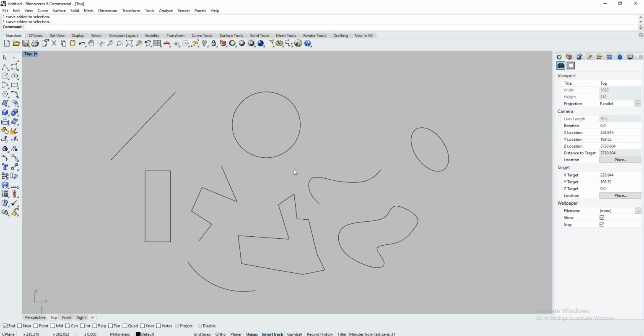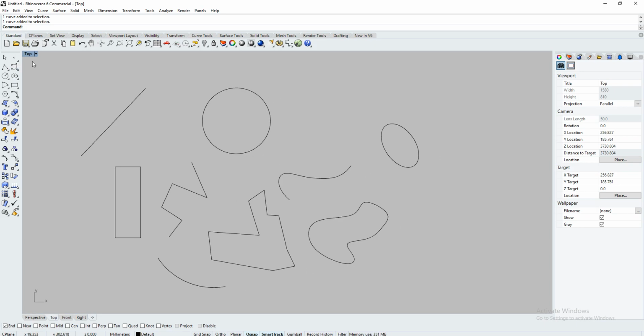So all closed curves have a seam. So if I create a closed curve, that's where the seam is, and you can snap to the seam. I've got the end snap on, so that's the seam right there. Can't snap to any other endpoint but there. When you create a circle, because my mouse cursor's down there, that's where the seam will be.